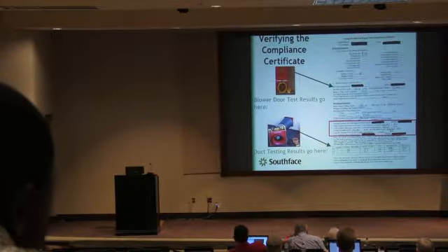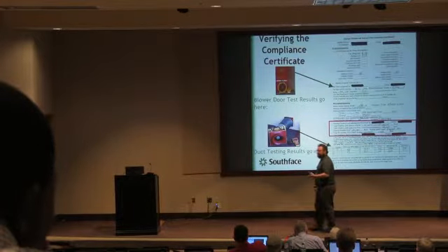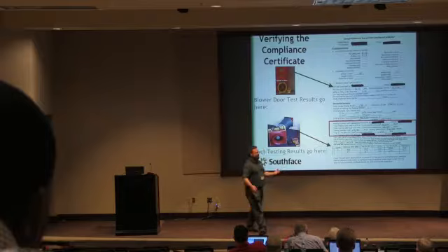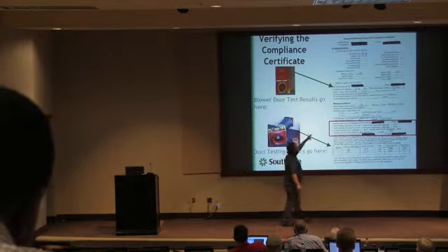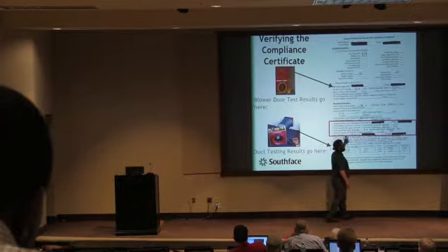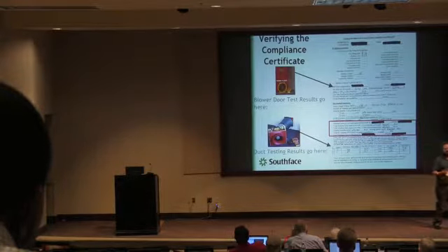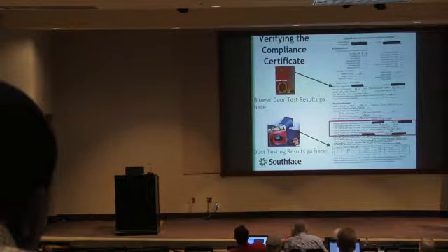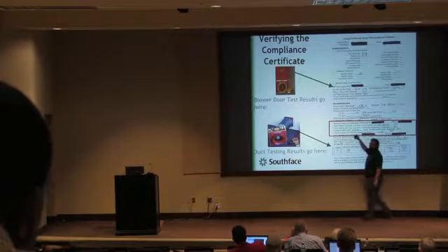Okay, so the last thing on this is we have this thing called an energy certificate, which is supposed to go in a new home and tells you all this type of stuff about the house. It tells you the R-values they put in, what they got on their blower door test, what they got on their duct pressure test, and it has a summary of the mechanical system that's installed. So you can't tell how they did the load calculation, but you can look at the model nameplate on the air handler and the outside coil, and you can know whether at least what they reported on the certificate is what's actually installed in the home.